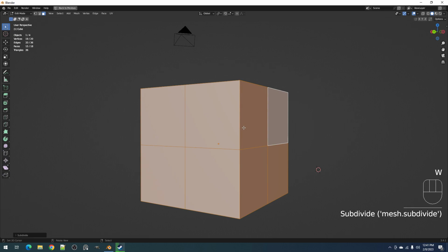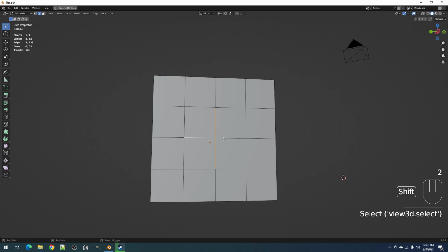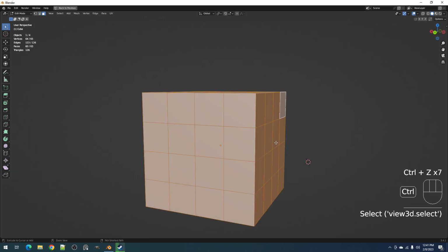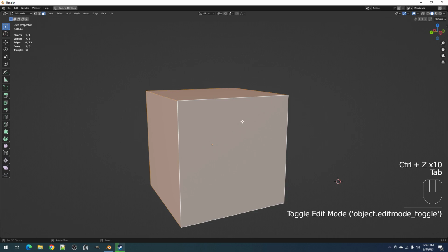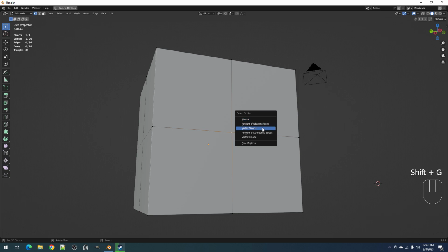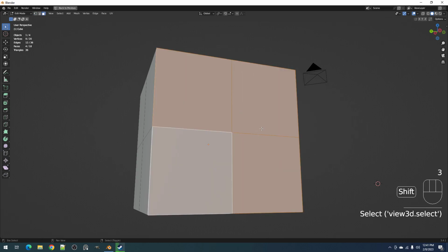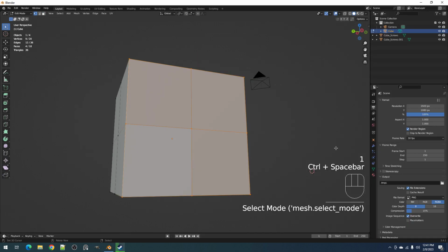Now we have pinning. With pinning, with panel cloth, I'm using mark sharp edges instead of vertices, because let me show you. If I, for example, use vertex groups and assign this as a pin to pin the result of the panel cloth,